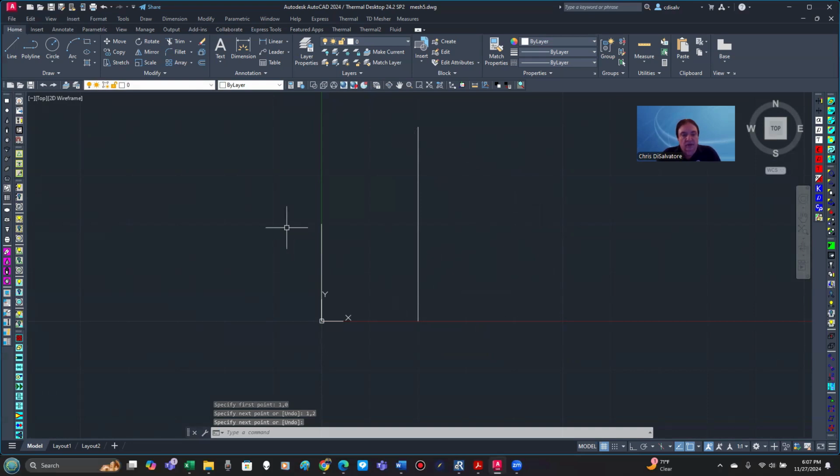Okay, so now that we've generated the initial features to create our surface, we can go into the rule surf command, which we can type in, rule surf. That'll pop up where you can select it if you want to, or you can just enter rule surf there. Now, there's something at this point you're going to want to be careful of when you generate the surface. You need to pick towards the same ends of each of your features in order for that surface to be generated properly. And I'll show you what I mean in a minute.